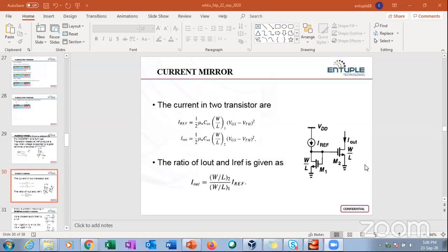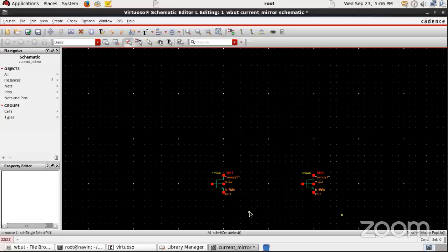In this circuit, you can visualize that both the gates of the transistors are connected, so the devices are connected back to back. Note that the source terminals have to be grounded. It acts as a common terminal. Here is how to make these types of connections in Cadence, in the Virtuoso tool.